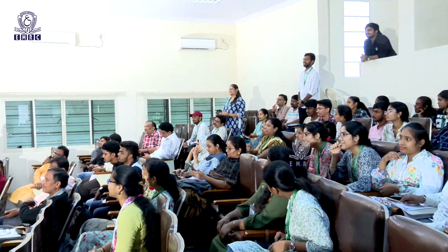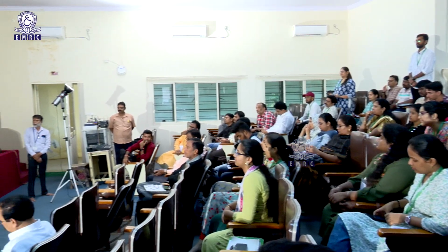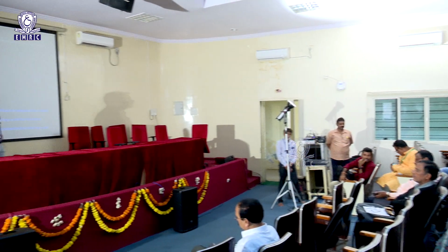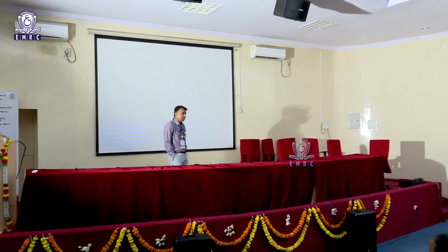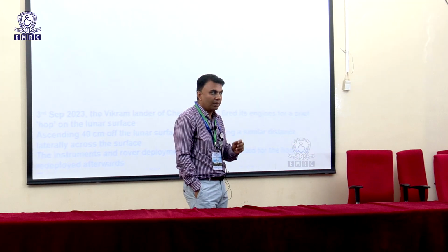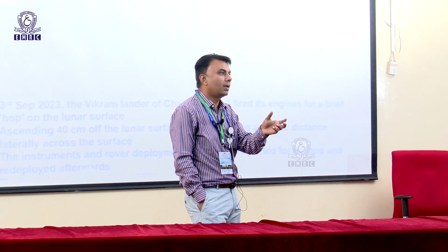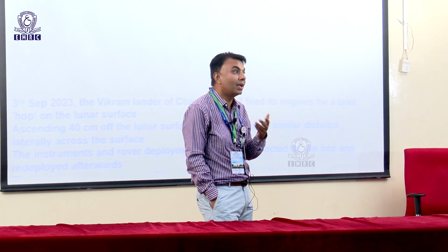Both are very great questions. First, congratulations on your great questions. See, when I say that NAVIC gives you better accuracy than GPS, there is a technical reason behind it. GPS is global coverage and NAVIC is regional coverage. The major error is called the position error budget. With GPS you will get meter-level accuracy like 4 meters, 5 meters, and for NAVIC I am claiming sub-centimeter.